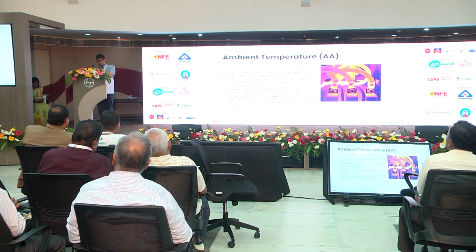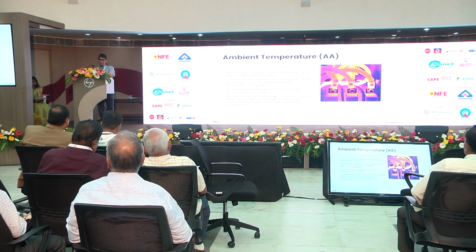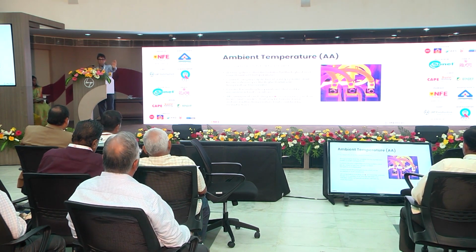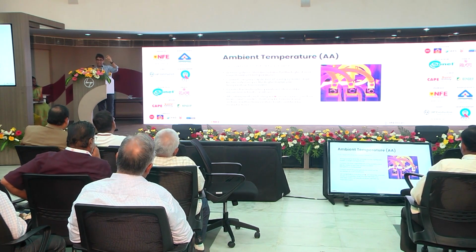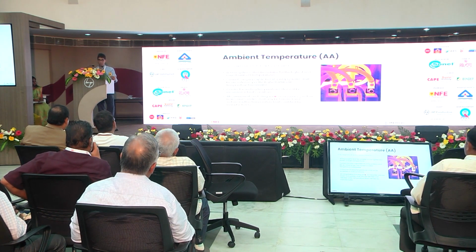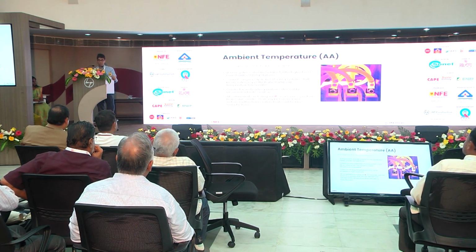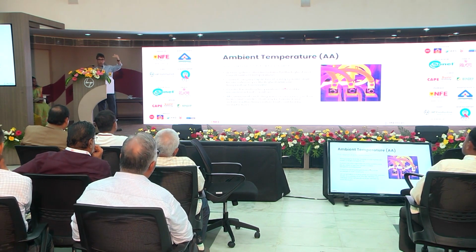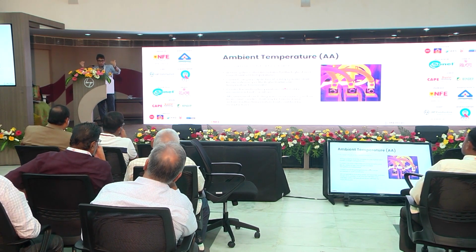So ambient temperature. Like I said, we all know that wiring systems emit heat. Now, the insulation on the cables is rated for a certain maximum operating temperature in continuous use. So the higher the ambient temperature, the lesser that gap. Annex S assumes a 30-degree ambient temperature for thermoplastic cables, which is PVC cables, and a 90-degree limiting temperature for thermosetting cables, which is XLPE. But if our ambient temperature is 40 degrees, then the temperature rise available for the cable is lesser. So you then need to derate the cable.